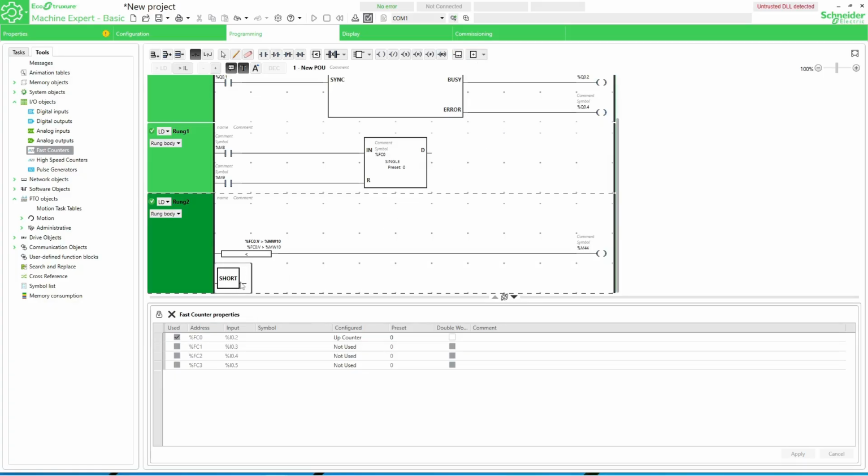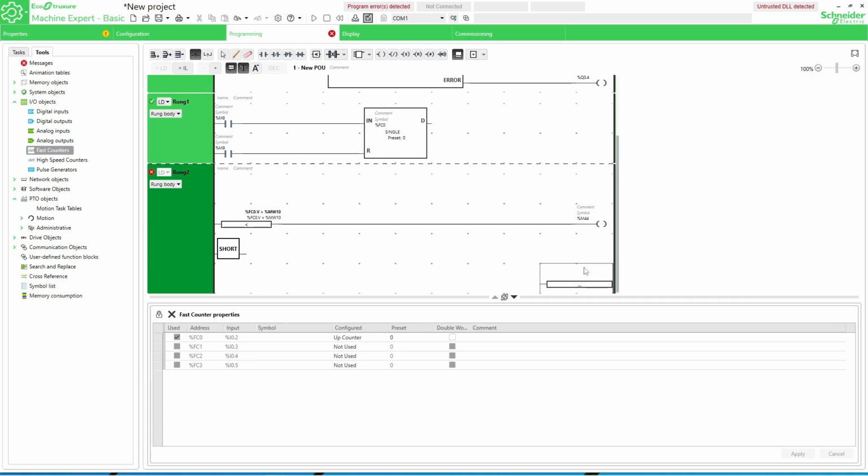In a new line, add a short block as input and an expression block as output. Here, input and output mean only left and right. In the expression block, we will assign the frequency value of the frequency generator. To access or assign the frequency value, write FRQGEN.FRQ. Then we will take the value of variable MW50 and use it as the frequency value. The DWORD function allows us to convert the value of MW50 to a double word.